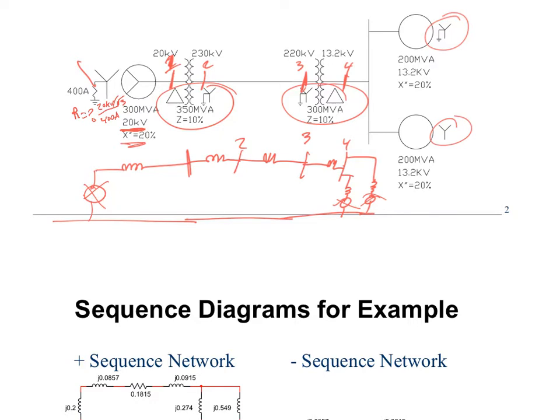The reason being is because if I have a generator here, and let's just look at one phase, if I want to limit the current through ground, this is 20 kV over the square root of 3. This is R. If I want this to be limited to 400 amps, doesn't that R have to be the only limiting device? The worst case scenario I'm going to see is a dead short to ground on a single phase, I'm limiting that to 400 amps by specifying that resistor to be 20 kV divided by the square root of 3 divided by 400. That's how I actually specify it. Okay?